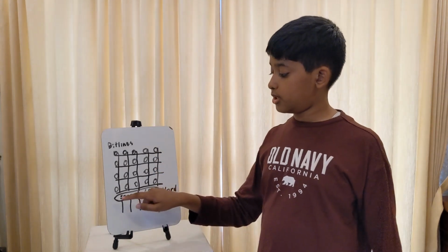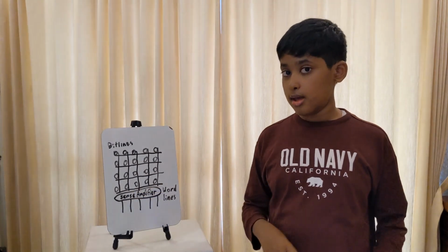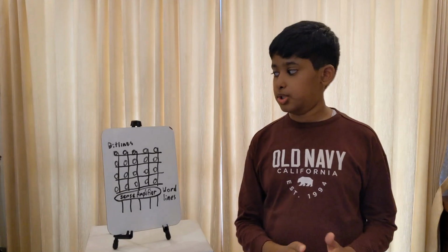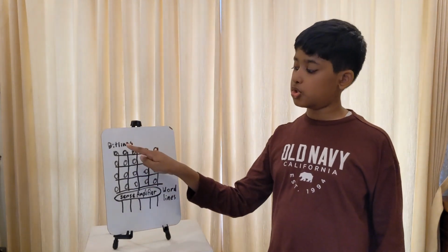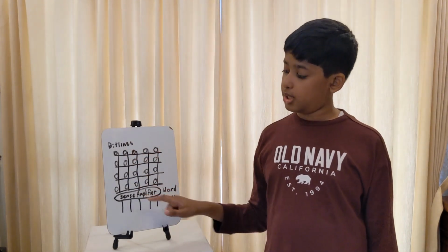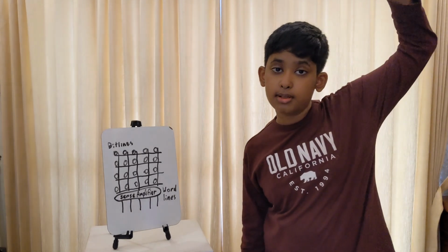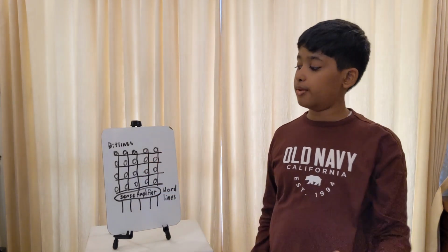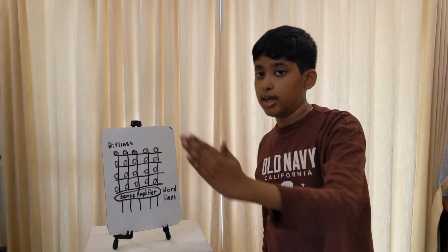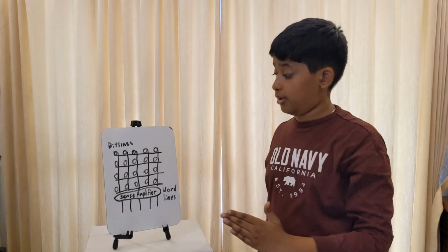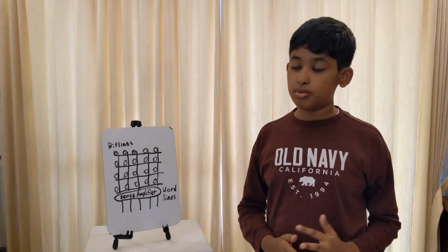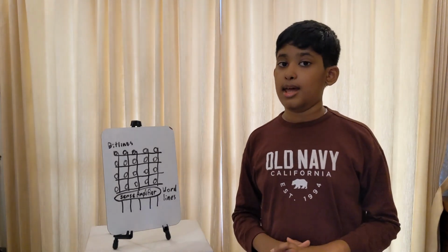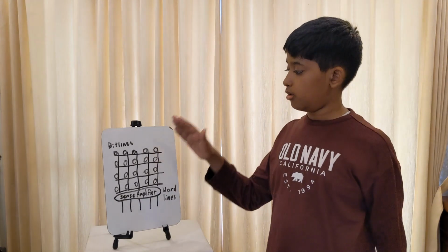You'll also notice this sense amplifier here. This sense amplifier essentially drives the voltages. If there's a tiny change downwards in this wire, the amplifier will drive it all the way down to zero. But if it goes a tiny bit upwards, it will be driven all the way to a high voltage, which in this case, let's assume is 1 volt. So, let's now discuss how reading can work using this grid.